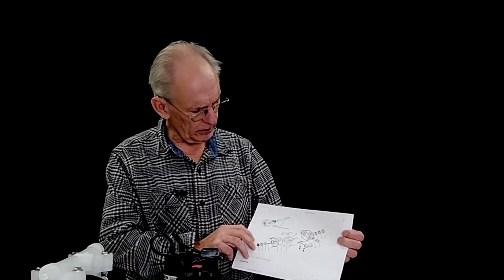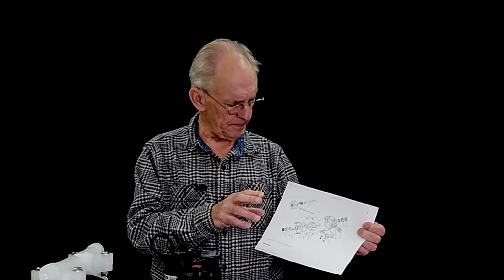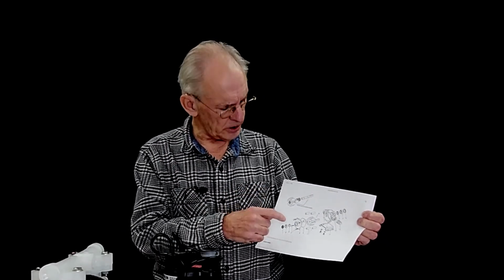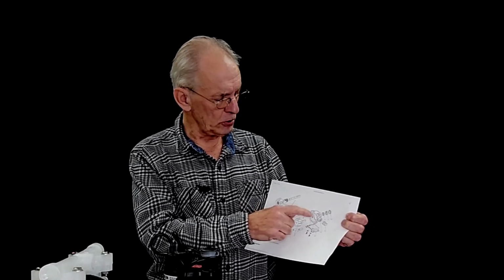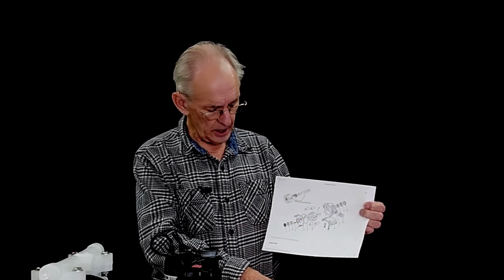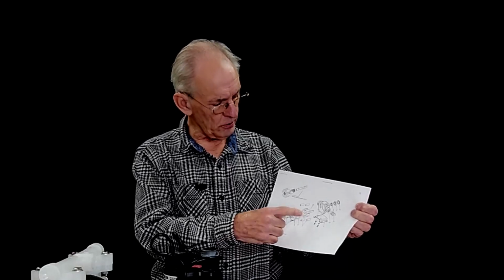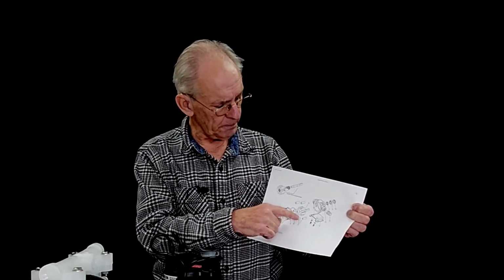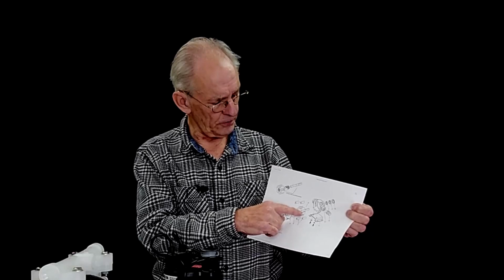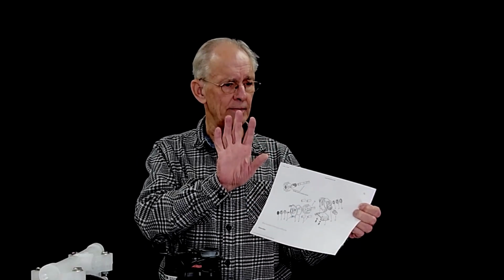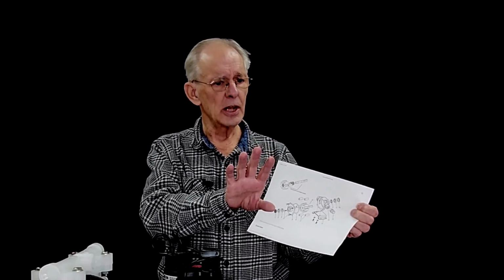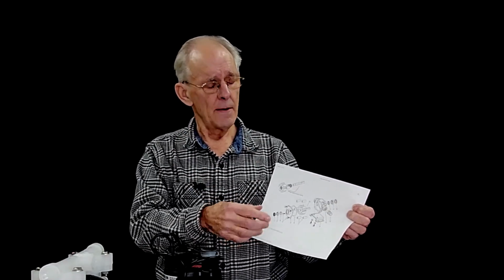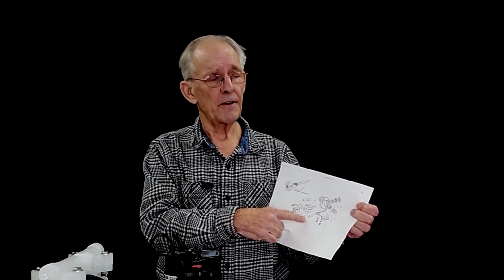So this pump, I could only find an exploded view, but this pump is a roller pump. This is kind of a hybrid. It depends on centrifugal force to keep the rollers against the outer housing. And like the vane pump, the rotor is not centered in the housing. And what it does is it creates cavities that expand and contract as they go around. But the roller is simply driven by the rotor. And the roller, if you think about it, it's being pushed by a stationary surface and then rolling against the outer housing. So the rollers tend to wear out quite fast.